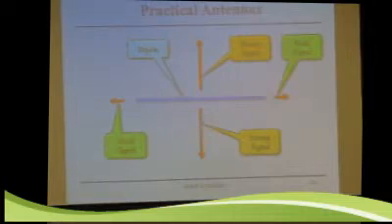An inverted V actually is closer to omnidirectional than the standard dipole is as well. Plus, again, most people use inverted V's for 80 or 40, and like I say, in those situations, you're not going to get all that much directionality anyway.